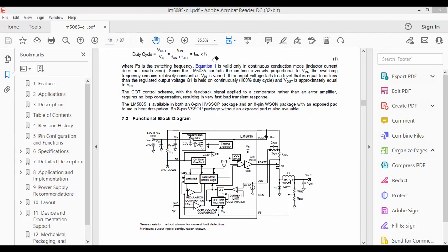So in order to satisfy that, you have to convert whatever input voltage comes here to a fixed voltage to drive this internal circuitry, which means even though it is a buck converter, in order to run its internal devices, it has an internal power controller. That power controller generates the voltages required for these devices, right? Otherwise, this 75 volts is too much for these internal logic gates and everything. They have this internal power supply, which is associated with the VCC pin.